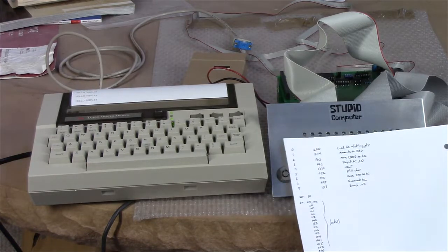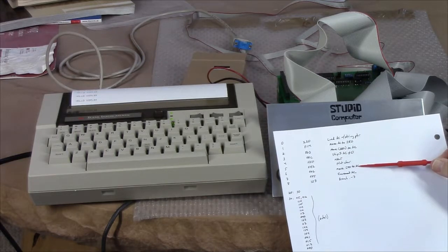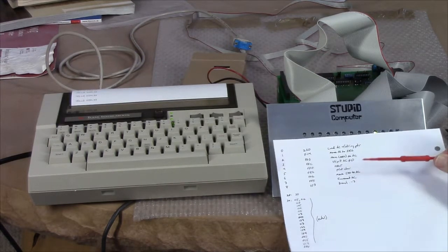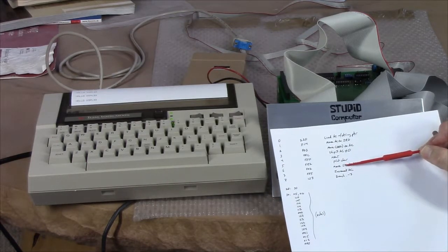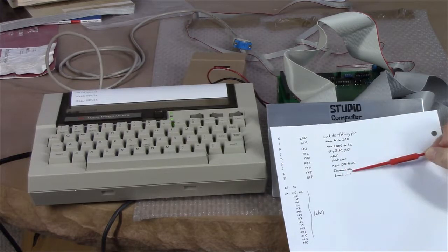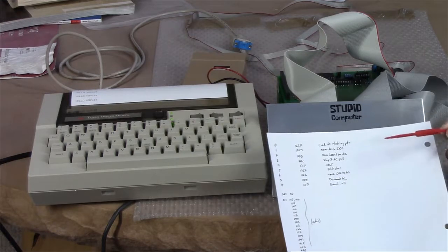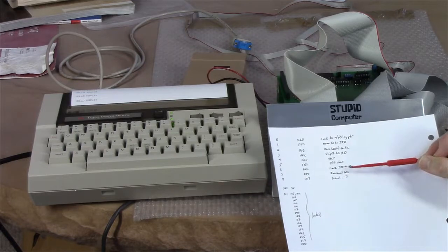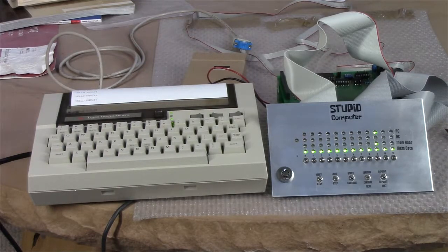For instance, right now, it's 2 instructions: move the indirect register to the accumulator and increment the accumulator. I may be able to say move the incremented value of the register to the accumulator and save an instruction here. You'll still have to move it out and move it back. But that would save the increment, or the decrement, by the way, instruction. So we'll see. It's all to be determined.